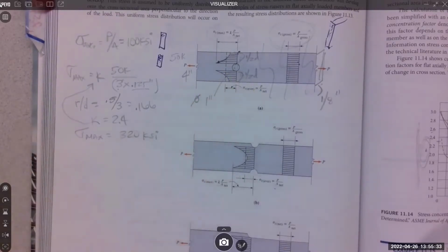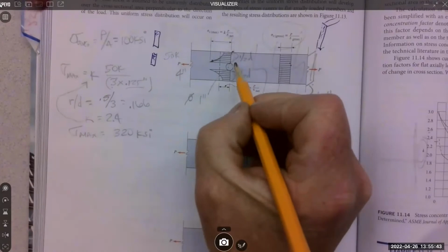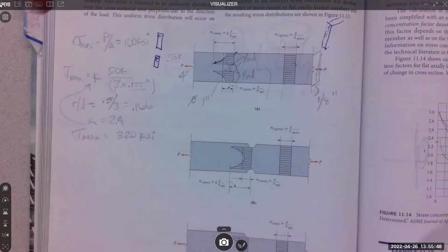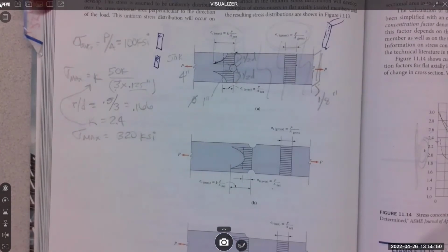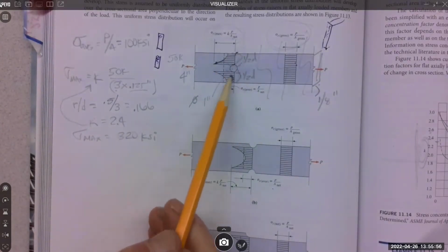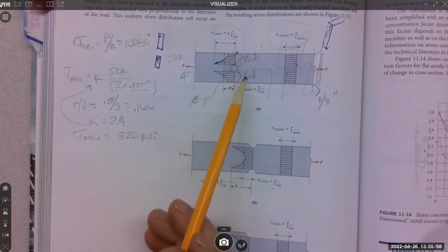That's why if you look at frames that have failed or are beginning to fail, or if you are taking bolts off of something, you'll see cracks propagating out of holes. It's very common to see this kind of action coming off a hole, because that's right where the stress riser is. What's interesting is sometimes you can make this hole bigger and the stress will come down.